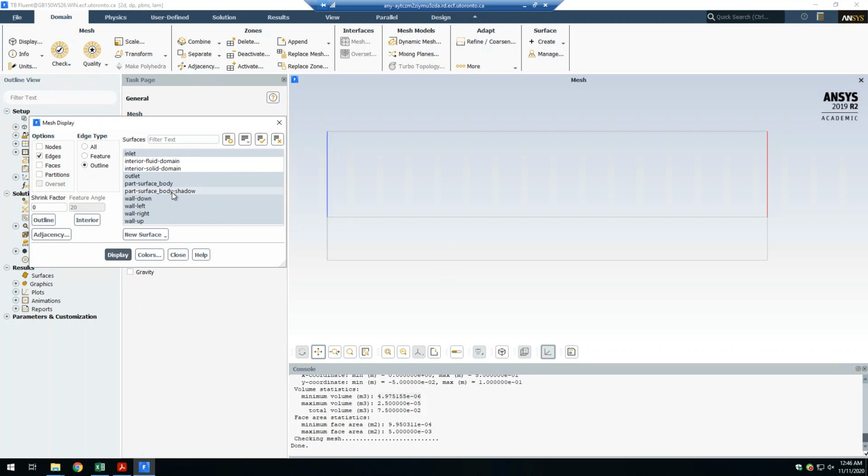But you can see another option with the same name and a shadow name. So what does that mean? Whenever you have an edge or a boundary between two different cell zones, Fluent automatically creates another line. It considers that line for one of the zones, and it creates another line at the same location with the same name but with shadow for the other zone. So it's just created by Fluent. It's the same as interiors, which, if you remember, are created by Fluent as well.